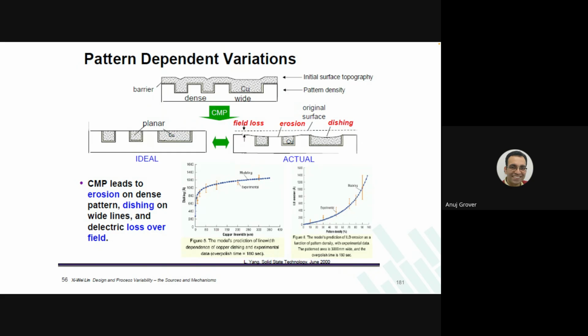What would I do? I will actually use 2 bit lines. I will not say, oh, for 2 CBL, I will increase the width, or I will put one more metal on top of this and then short them. That is not how you will get 2 CBL. In different process conditions, it might be 2 CBL, it might be 2.2 CBL, it might be 1.8 CBL. The variations will be very, very large. So you model that 2 CBL by actually using 2 different bit cells next to each other and connecting their bit lines.